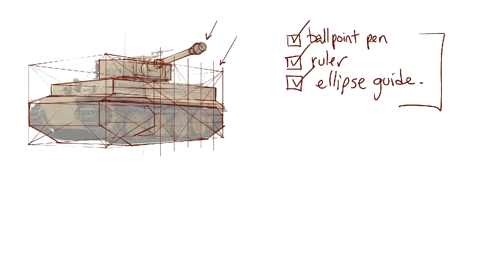Of course, when you're actually getting into the more specific lines that actually make up whatever it is that you're drawing, not just blocking in forms, I do want you to start using your 0.5 fine liner, or felted pen. And especially for accentuating certain line weights, you will probably find that to be of great benefit to you, just because you'll be able to separate those lines much more easily from the underlying ballpoint framework.